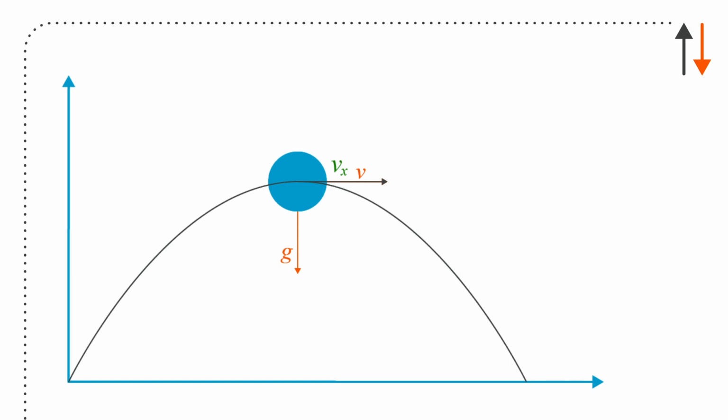Tangential velocity at the top of motion is going to be Vx because that's the only motion going on, and that's the tangential, so that's coordinate agreement. Then here I have u_r, u_theta, which describe the two velocities, so I'm going to have Vr, V theta. You can see right away why I wouldn't want to use an r-theta coordinate system for projectile motion. And most of the time when we did projectile motion, we used Cartesian coordinates.